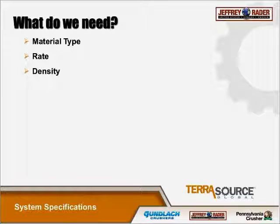We need density. Minimum density is going to determine the largest volume of material to be conveyed. That's going to give us the feeder size, among other pieces of equipment. Max density is going to dictate the highest tonnage to be conveyed, which helps us size the blower and pipe size. We'd like to know the maximum piece of material, and that goes back to the feeder discussion. An 8-inch piece of material won't fit through a 6-inch pipe. It's as simple as that.